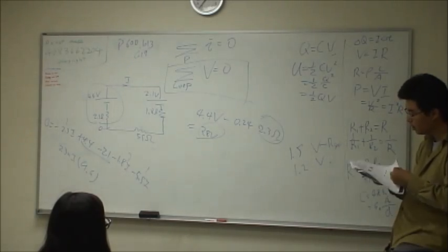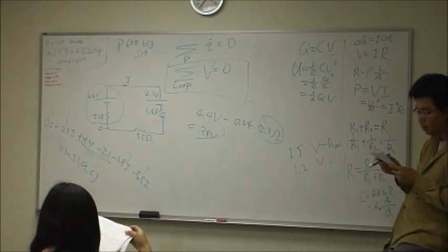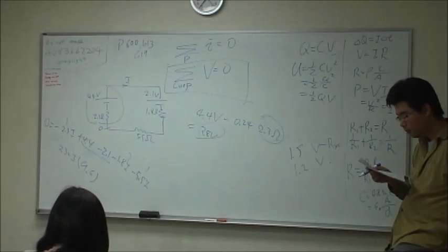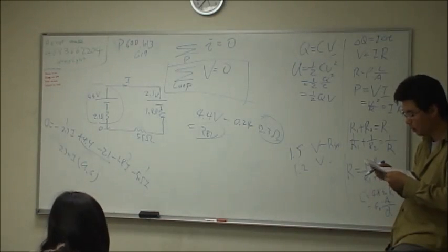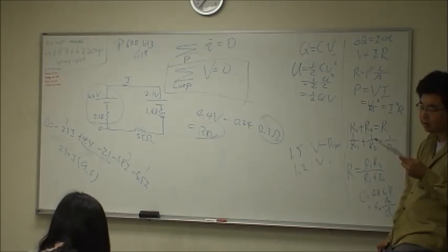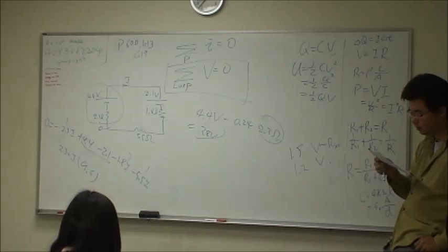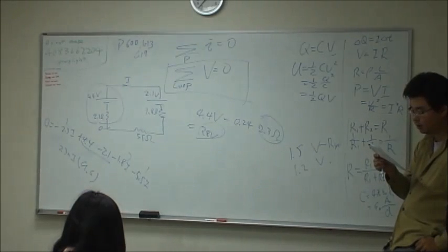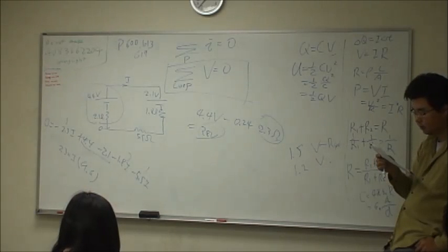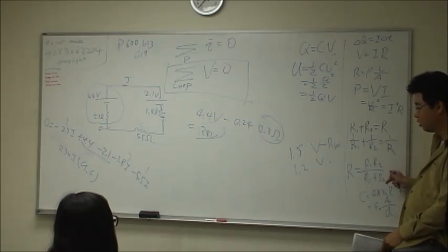Okay, so that's page 641. Let's keep going. Okay, table 28-1, that's very important. Let's talk about the different resistance and the capacitor. In series, resistance just sums up. If it's parallel, then it is 1 over R equals the sum of 1 over R. Capacitor is just the reverse of resistance in terms of parallel or series. If in parallel, it sums up, and if it's in series, it's 1 over C equals the sum of 1 over C. And if it's only two of them, multiply on the top and sum on the bottom. That's the normal case, right?